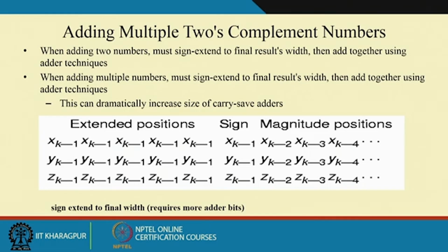In multiplication, the first partial product is the bitwise ANDing of the multiplicand with the LSB of the multiplier bit. Then for the next bit position, the corresponding multiplicand value is shifted by one bit and then added.